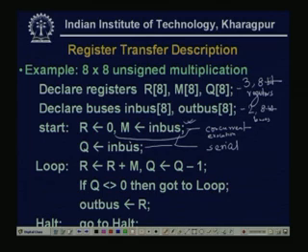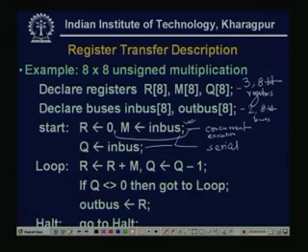As there is only one input bus, the operations in bus to M and in bus to Q cannot be performed simultaneously, because there is only one 8 bit in bus. So, after the data is transferred to M, in the next clock cycle the in bus is transferred to the register Q. So, these two operations are carried out serially.